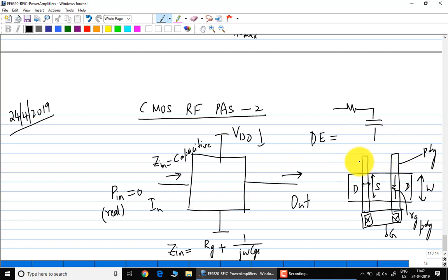You can reduce this in many ways. For example, you could have chosen to connect these on metal. Metal is much less resistive than poly. I could do a dual gate connection. I'll connect the gate signal from both sides, in which case I would cut the poly resistance by about half, correct. What else can I do? I can reduce the width of each finger. If I double the number of fingers from 2 to 4, I'll reduce the poly resistance again.